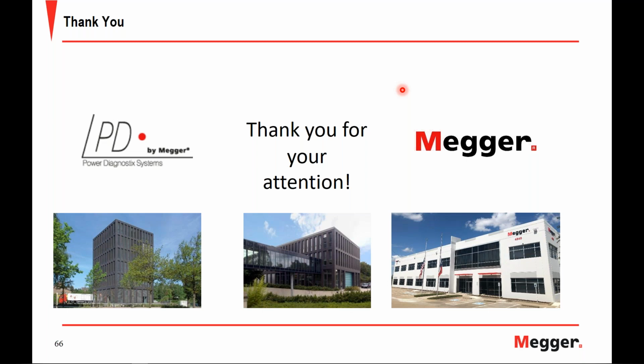All right, as a follow-up, is it possible to test medium voltage cables with ICMflex, and will the results be relevant? Sure, absolutely. So the ICMflex is also capable of testing medium voltage cables while performing partial discharge and tan delta measurements as well. And those results would be relevant. Those results would be useful, as with just performing a tan delta or power factor measurement with any other instrument on your cable, and partial discharge testing.